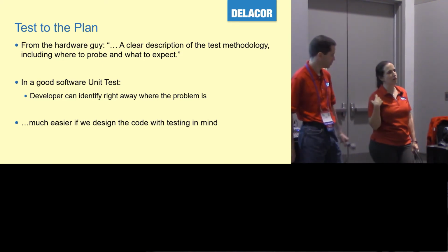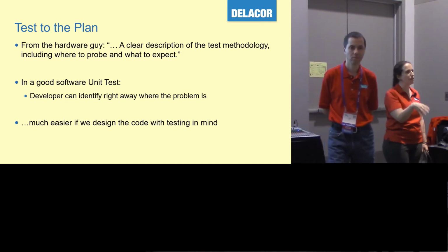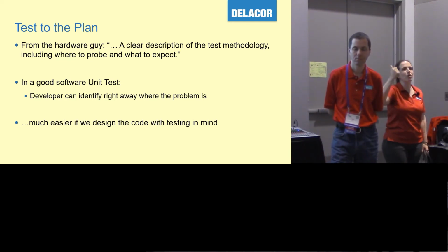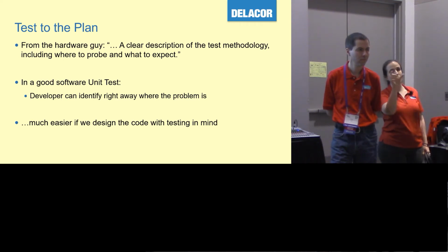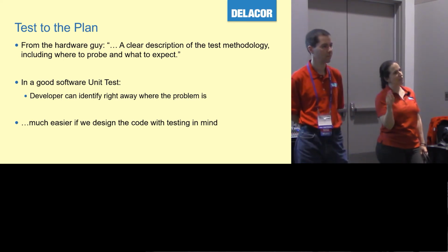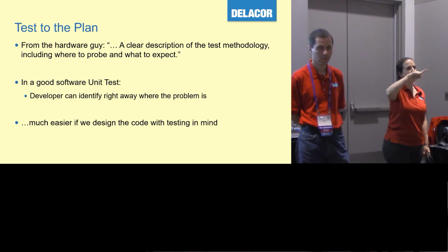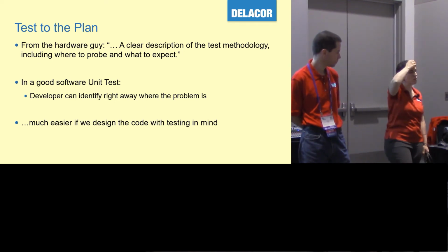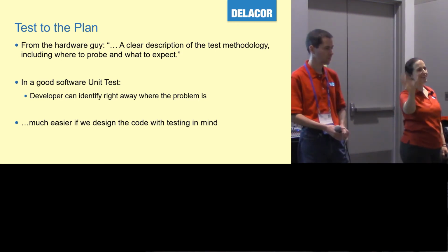One way that we do it at Delacor is we use bookmarks. For example, in the comma separated value file example, there are going to be different VIs and different sections where I am defining what the titles of the columns are, and another section where I define what the range of the settings are. So maybe on all those VIs, I have a bookmark that says setting definition or CSV file definitions, and I include that bookmark on the unit test. So if that unit test fails, I have notes on how to figure out what are the VIs involved beyond the one that's on the unit test, because this could have been related to something else. And two, I know what other siblings of this VI I need to go check.